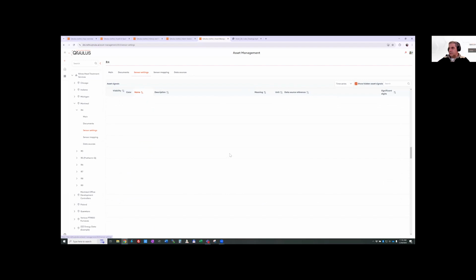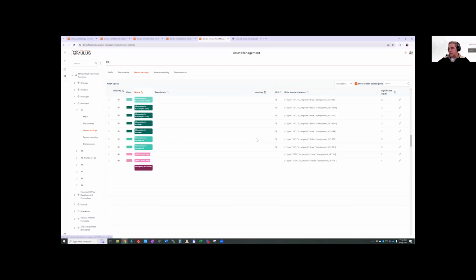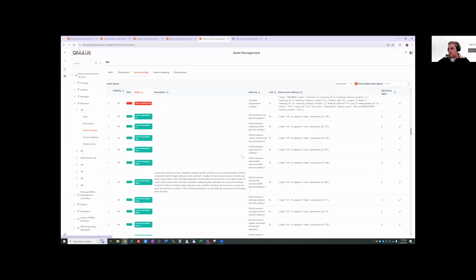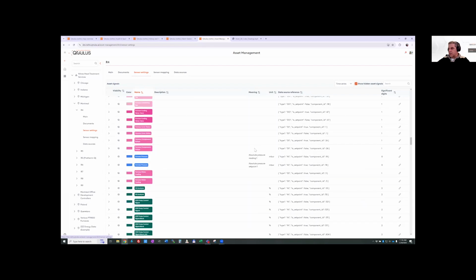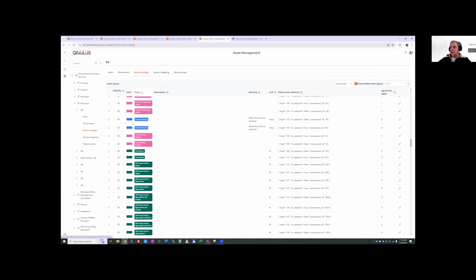Sorry, I went too fast there. Hold on. I want to show you a nice little group here. The group meaning I chose furnace pressure, and this is furnace pressure reading. A furnace pressure reading is the device, a pressure transducer. It is a physical device that gives a number, and it gives pressure in this case, and it gives it 24 hours a day. Running a cycle, not running a cycle. Cover open, cover closed. You always have a 4 to 20 milliamp signal.